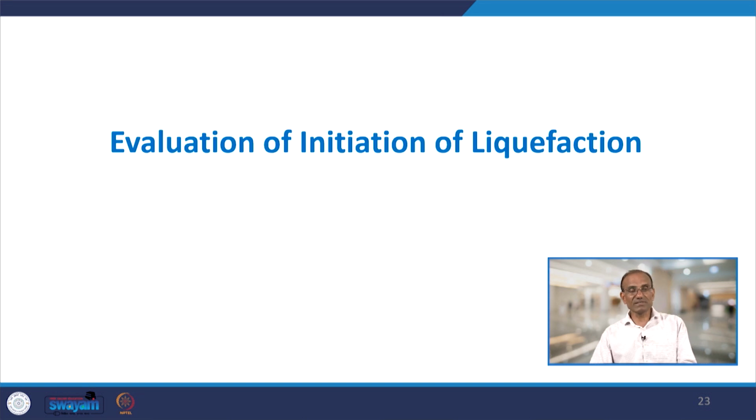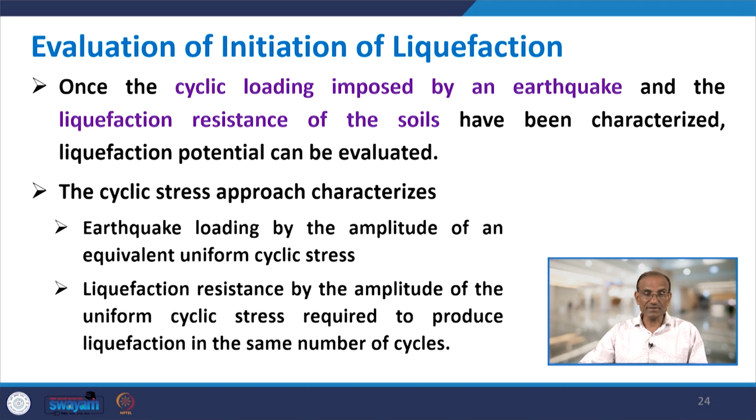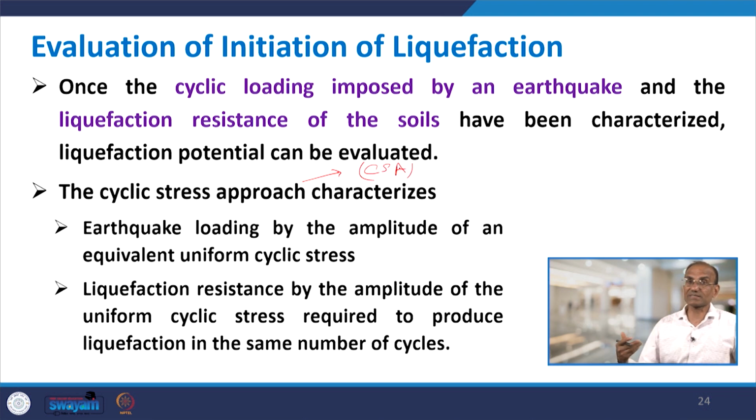Now, we have the last part of this lecture, which is on the initiation of liquefaction. How this liquefaction starts, or is initiated, in the field, we are going to discuss one by one. Once the cyclic loading imposed by an earthquake and the liquefaction resistance of the soil have been characterized using the same parameter, normally the cyclic stresses, liquefaction potential can be evaluated. So, basically we are summarizing it here using the cyclic stress approach, in short CSA. In the next few slides we are summarizing the steps of the CSA.